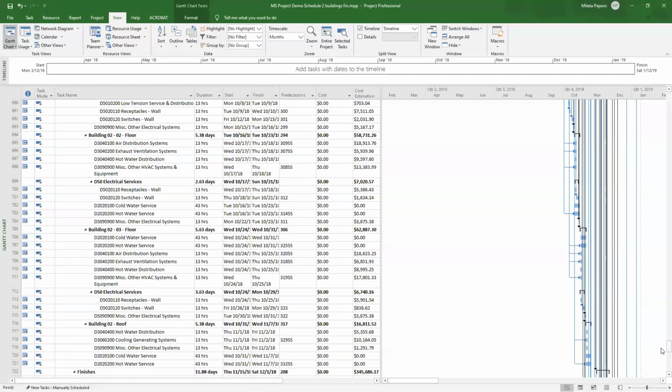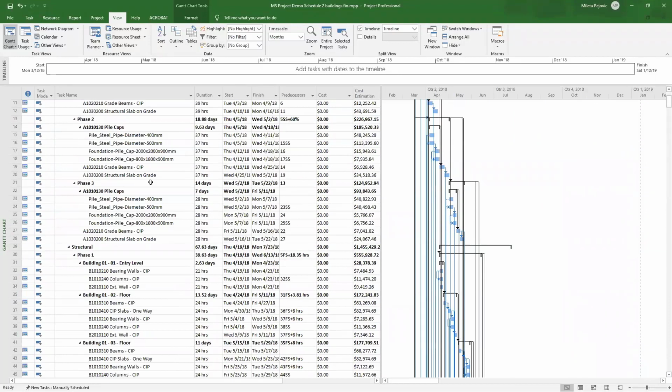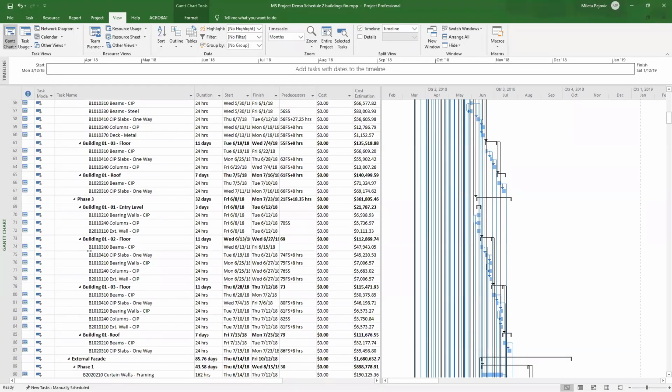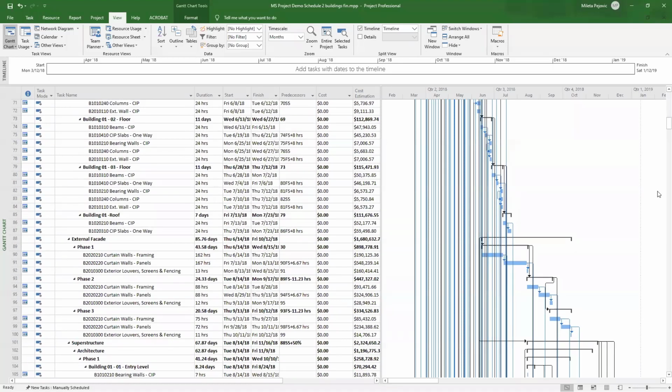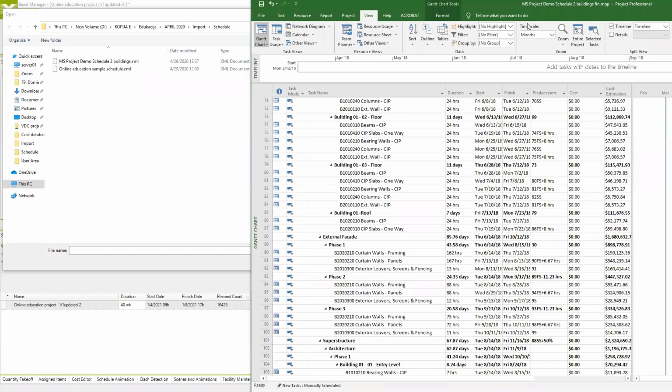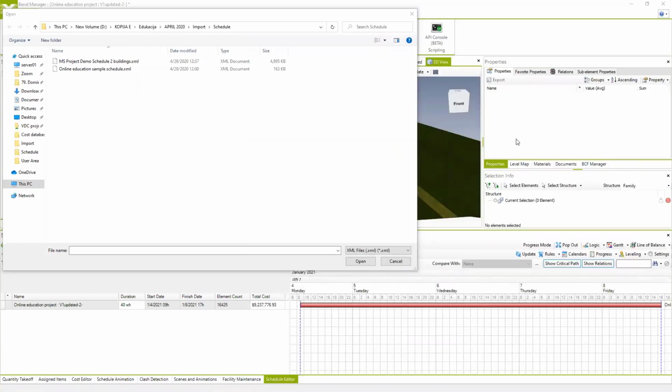And this kind of linking a BIM model with the tasks could be really, really time consuming for a schedule of this size. And of course, we have even used schedules with several thousands of tasks, but I'm going to show you some advanced options to link the schedule and the tasks with the 3D model elements in this case.